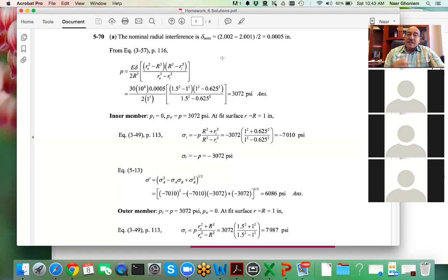M itself was okay, everybody got the M, but then M over I using singularity functions. If you didn't use singularity functions, you can divide up the shaft into 3 different pieces. But if you do that, then you have to have constants of integration on every piece, and then you have to piece them together and solve for 6 constants, which is not really very nice.